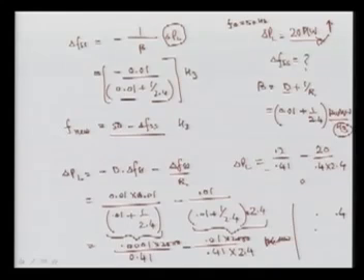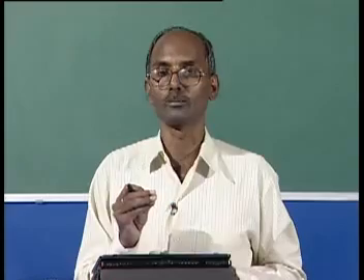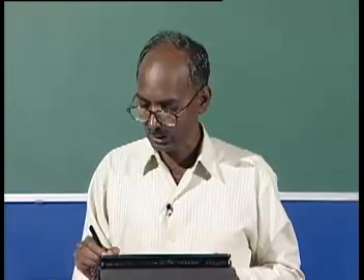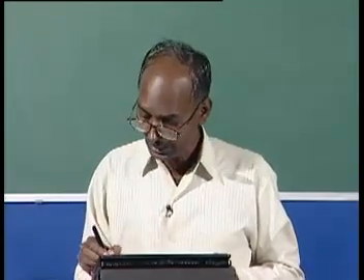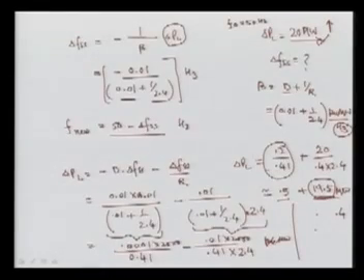So you can see this value here is very small, approximately 0.5 megawatt, and the remaining value is positive, so we can say 19.5 megawatt comes from here. So now we can say the net load release is very small. This component is this megawatt we are talking about. So the lion's share is coming from the governor action, so it is taking care of that.